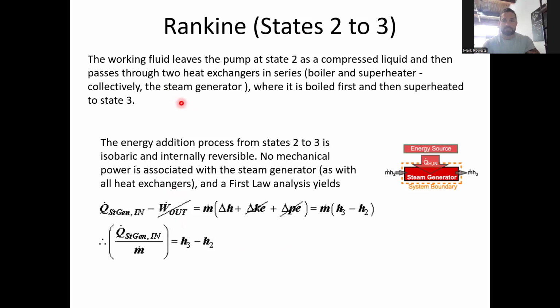Okay, when we look at state 2, this is going to be our heating process. So we're taking this subcooled liquid and we're heating it to a superheated vapor. The working fluid leaving the pump as the compressed liquid passes through a series of heat exchangers. We have a boiler and a superheater.